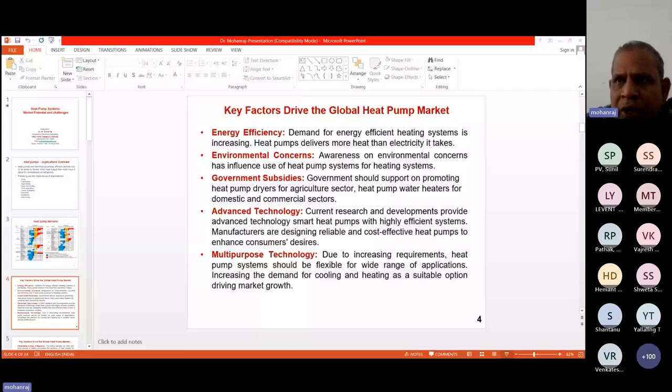Some smart technology can be recommended and used. For example, the evaporator temperature can change according to the ambient conditions. Such mechanisms can be provided, changed automatically with the help of automatic electronic expansion valves, which may be interfacing with the ambient condition. So according to the ambient condition, the evaporator temperature can be automatically shifted from lower to higher temperature, and they will maintain the operation according to the climatic conditions.